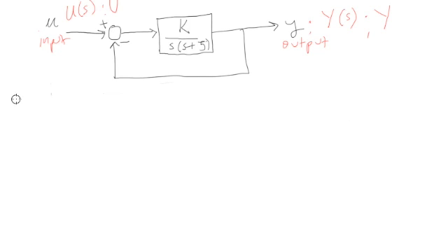So similarly, we know that the overshoot, MP, is the exponential of minus pi times the damping ratio over the square root of 1 minus damping ratio square. So this is not E, this is damping ratio. So this value must be smaller than 0.1. So if I took the log of both sides, I get a negative number, so there is a minus sign here, and I have to then multiply both sides by -1. So watch out if you do this simple math trick. It's easy, but usually you can skip this easy point. If you multiply everywhere by -1, you have to invert this smaller than sign. So that's a common mistake that we usually make.